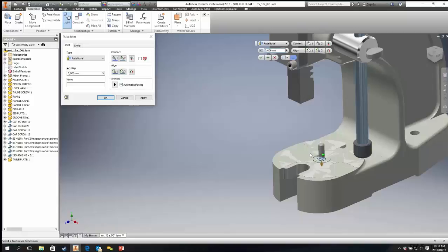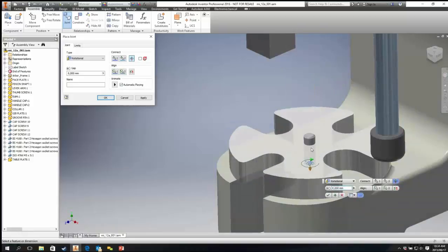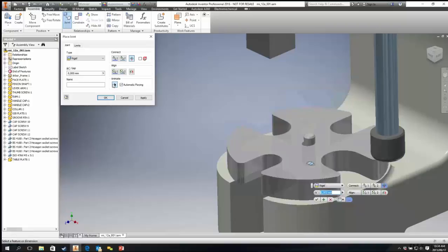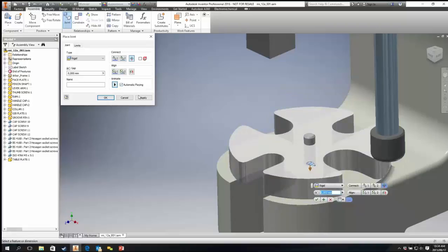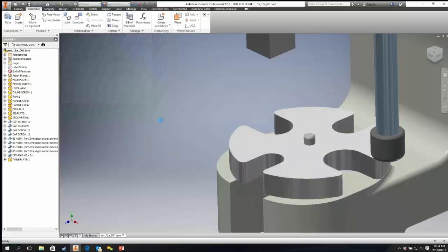So if I had to just switch this across quickly, you'll see that I can toggle this also from top to bottom, but it's still able to rotate. If I wanted to stop that, I can say, look, I want to align with this arrow over here, this face with that face. And now it knows that this is the resting position. And now I want it to stop moving to make it a rigid connection. When I apply these things, you see that it's trying to move, but it cannot, and that's why the vibration is visible. So if I had to say OK to this, nothing will be able to still move.